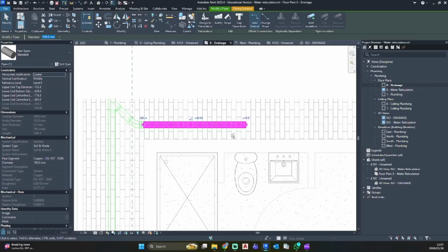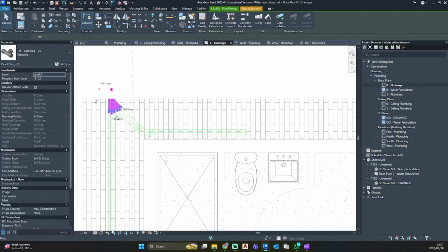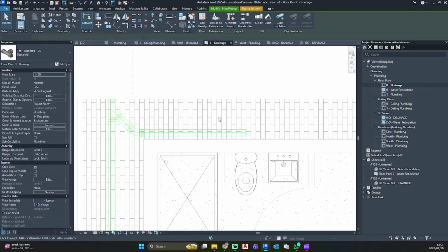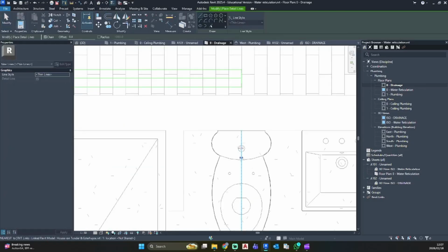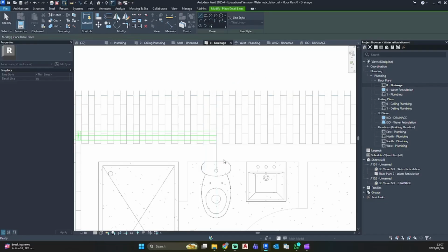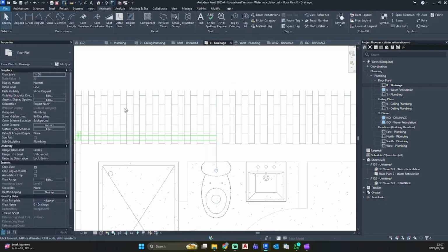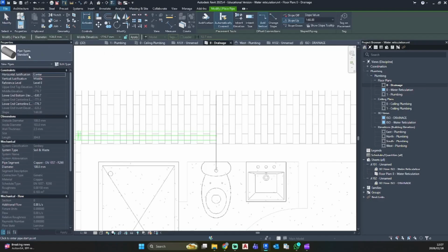Okay, I remember I have a photo that I just found on how this looks. I'm going to bring this back. I'm going to draw a detail line on this, and I'm just going to take it out like that. Okay, so now I'm going to go systems, pipe. So let's go inherit elevation.